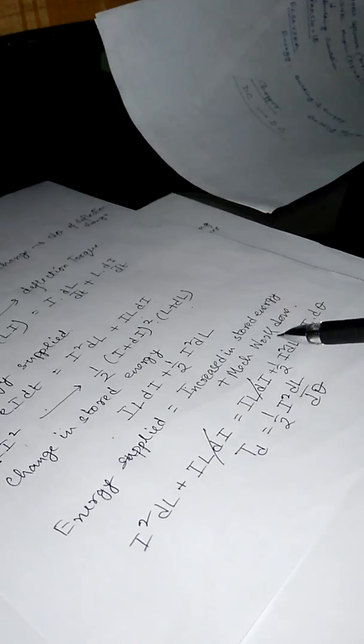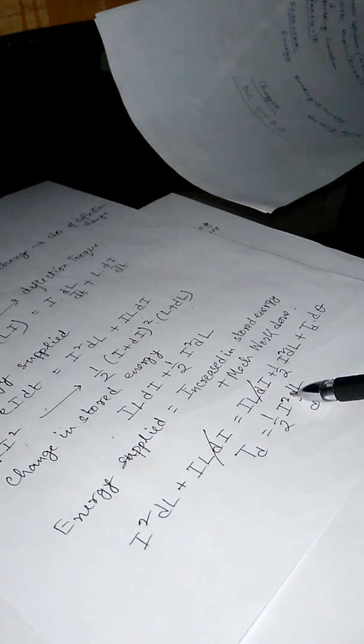That means from this point of view, the deflecting torque is dependent on the amount of current flowing through the coil, and for that there is the deflection theta. This current going through the coil is going to electromagnetize the coil, that electromagnet is going to attract the iron vane, and the pointer is attached to the iron vane. So the current is related to everything.